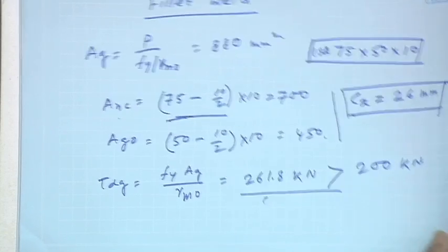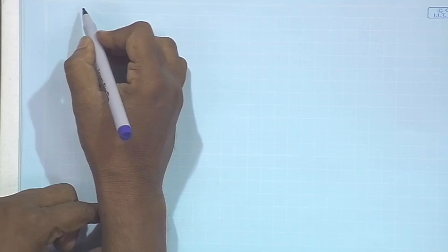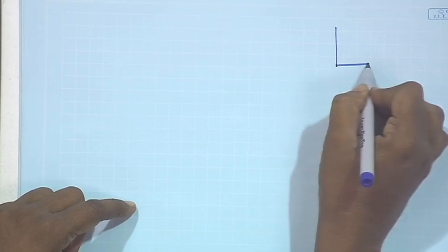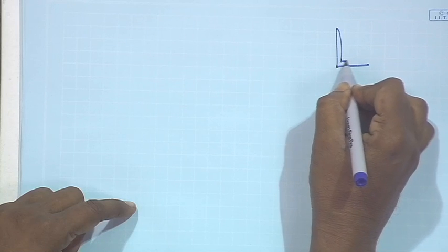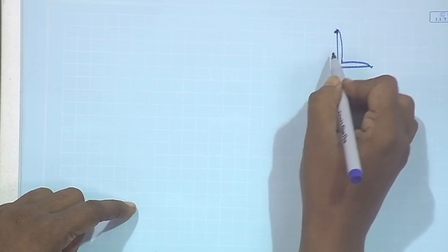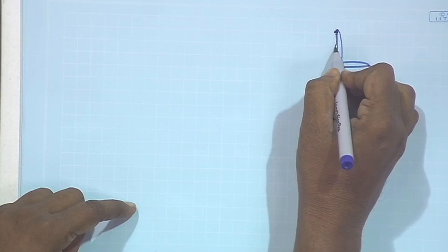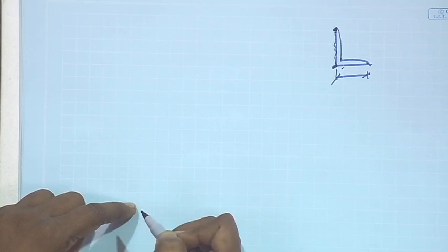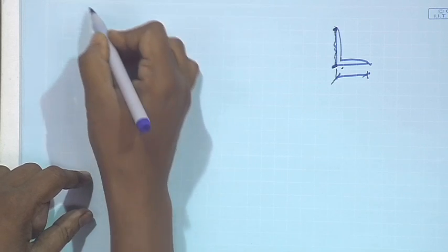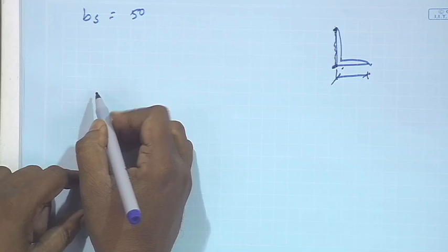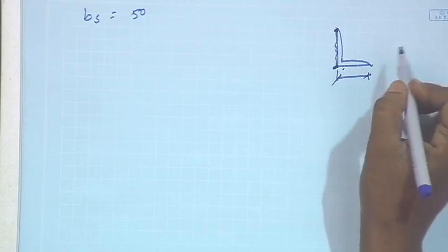Now, we will find out the strength governed by rupture of net section. So, in this case shear lag width will be different from bolt connection, because here it is connected by weld in these two directions, as well as it may be connected here. So, shear lag distance will be this much, right. That means, the shear lag width will be here 50 mm, and we do not know the distribution.